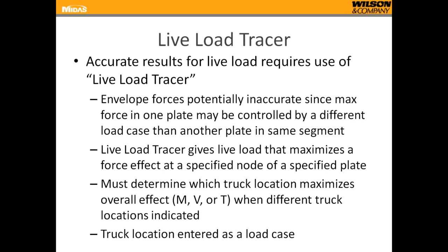Spreadsheets were set up to process the data efficiently, and the live load forces required, again, the use of this live load tracer feature. I mentioned this a couple times, so here's a description of what this tool is. Envelope forces potentially are inaccurate since the maximum force in one plate may be controlled by a different load case than another plate in the same segment.